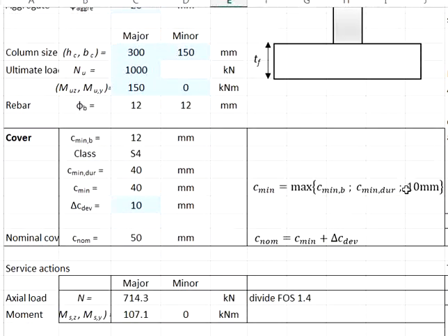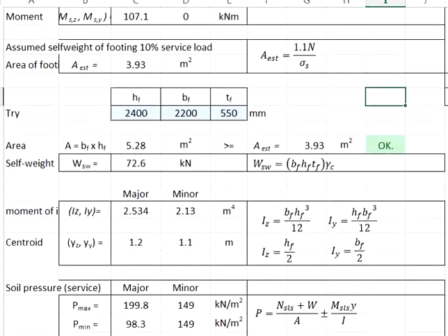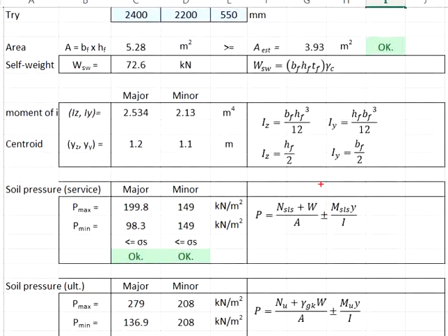The process of estimating the suitable size of the pad footing might not be as direct. It starts with estimating the minimum contact area of the pad footing on the basis of the axial load only. However, don't forget to take into consideration the effects of the moment.